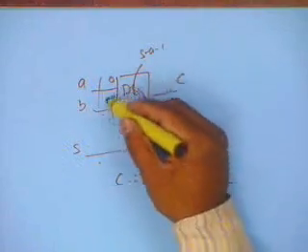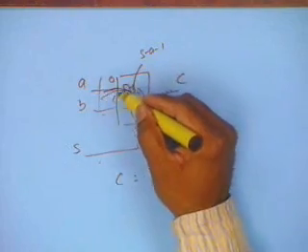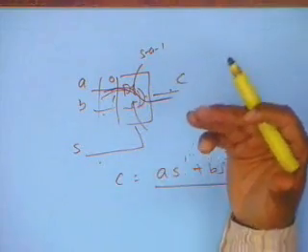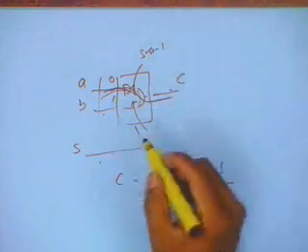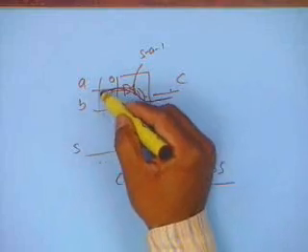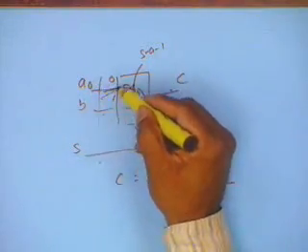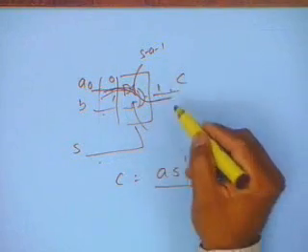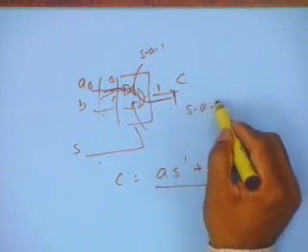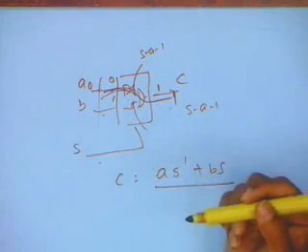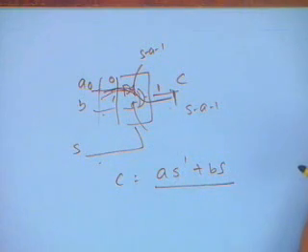Because let us say this particular node is stuck at 1, and I am testing, my test vector essentially sensitizes this path, because each of the test vectors is going to sensitize a path. We will talk about that later in detail when we talk of path sensitization. But the input I am transmitting from here is 0. I sensitize this path and I am transmitting zeros, but I get a 1 here, so it will appear that this is stuck at 1. Though the node that was stuck at 1 was somewhere in between, this may appear as stuck at 1, and I may be able to find this fault.